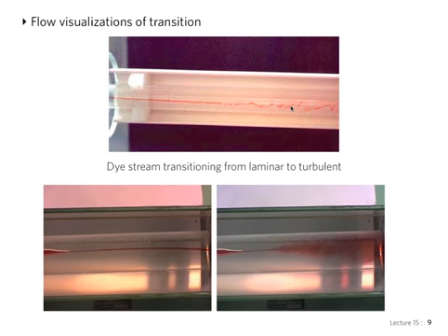This is the instantaneous picture of the little eddies, the sinuous motions that he talked about. On the left you have a laminar flow, and on the right a turbulent flow. He found that he could see this laminar situation for Reynolds number less than about 2000, and the completely turbulent case for Reynolds greater than about 4000.